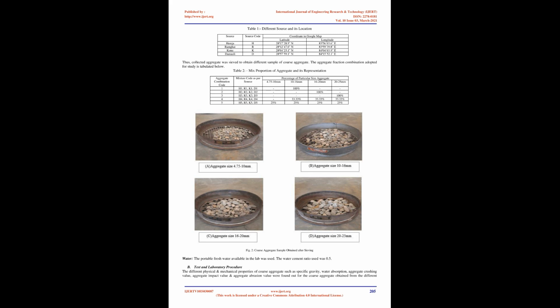Generally, the concrete grade used in the structural components of residential buildings is M20, 1:1.5:3. As per the drawings approved from municipal and IS 456:2000, the grade of concrete used in structural member using reinforcement must not be below M20. So, the nominal mix used for the study is M20.